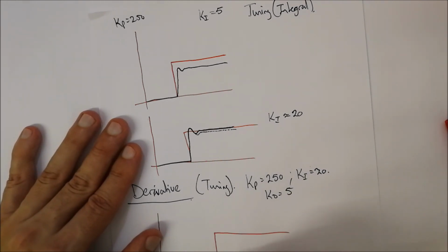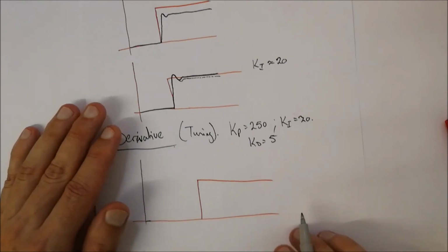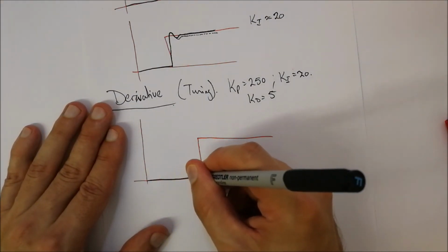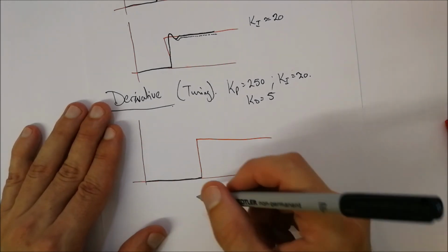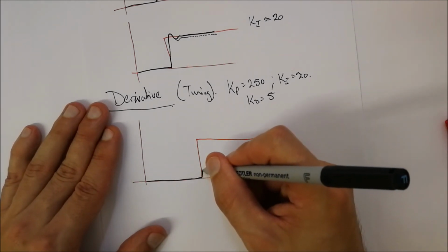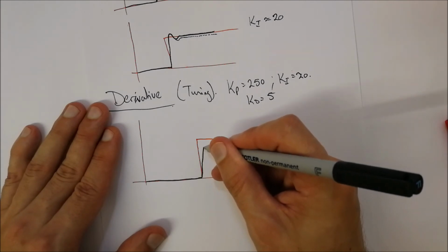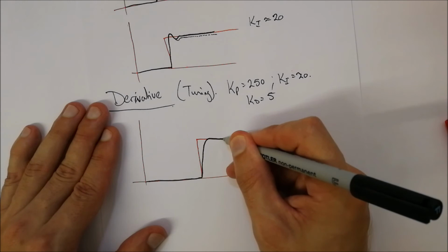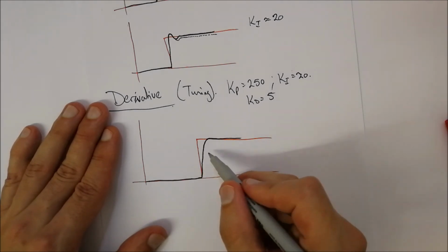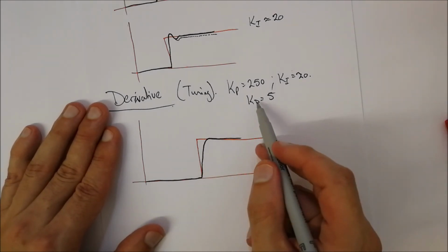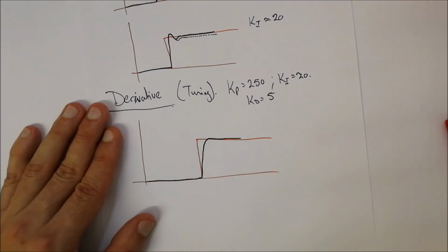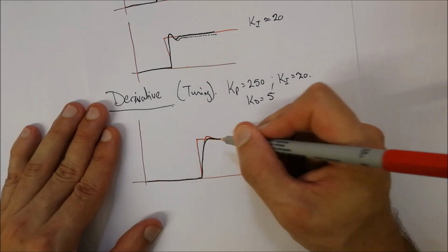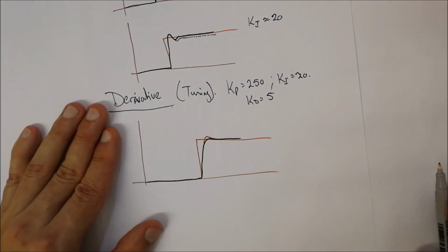And what's going to happen is that it will get there to the point where the step response starts increasing, and it will eventually make that overshoot not happen. It might be that it overshoots a little bit, so therefore you would increase your Kd value. If you find that it goes over, it might do that type of shape, which might be considered acceptable.